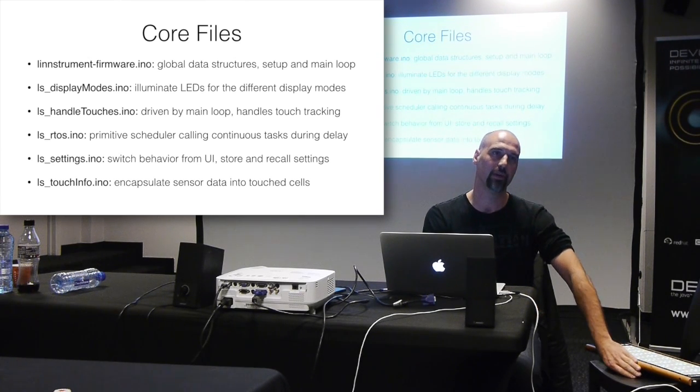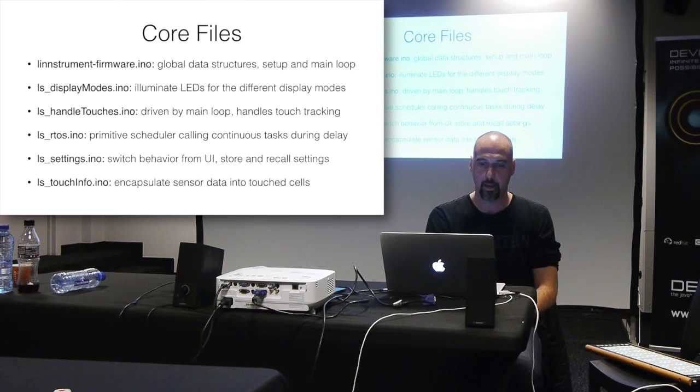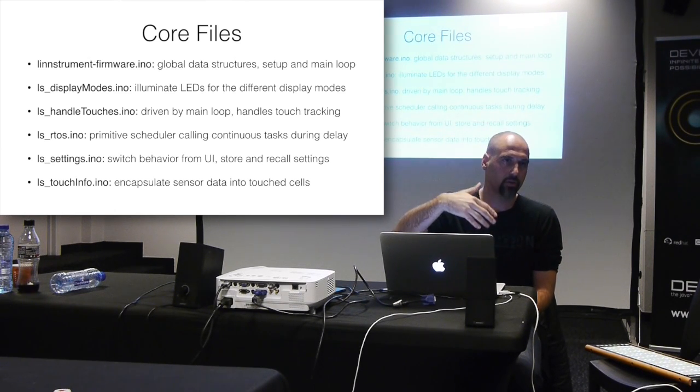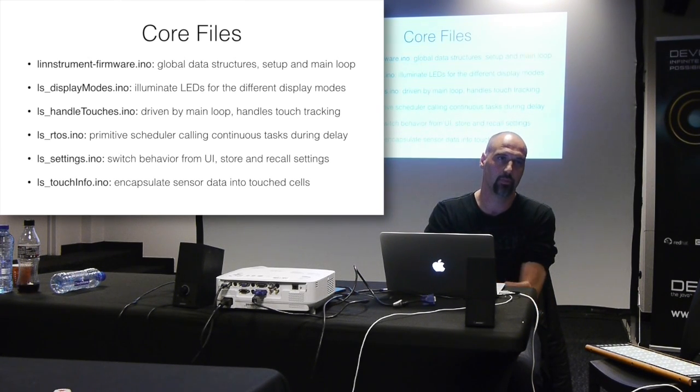Well, it's got its internal delay methods. So if we realize that it's done, then we might do an actual delay there for a little while until we know that we actually have to refresh the global functionalities. But it doesn't matter because the CPU is always running at 100%. So you can just loop there eternally and then break out of it when you know that the actual time spent is the time that you wanted to wait. That was the question: how do you know the actual time you spent? Because it's got a counter of current time since startup, both in milliseconds and in microseconds. The tricky one with microseconds is that it rolls over after 70 minutes, so you've got to be careful about handling that correctly.